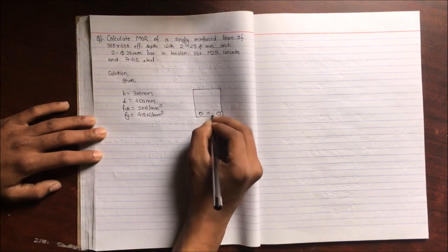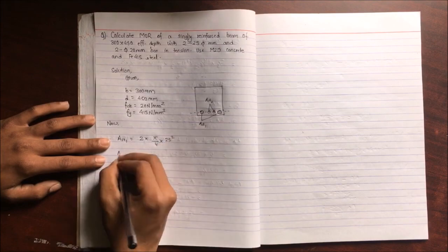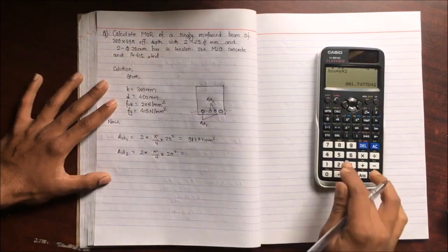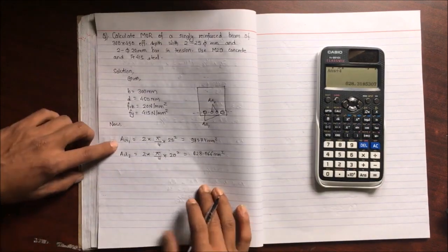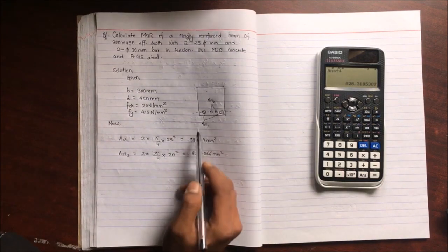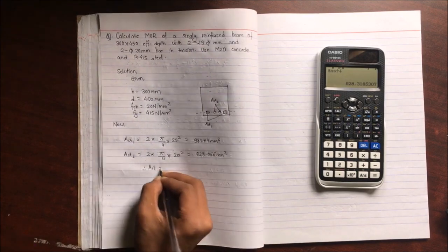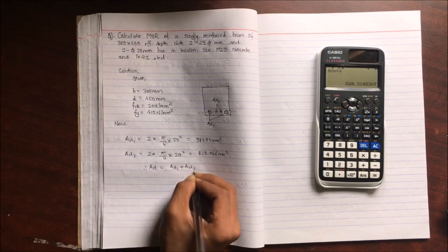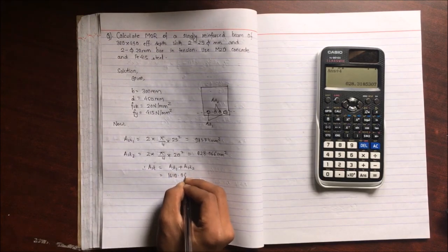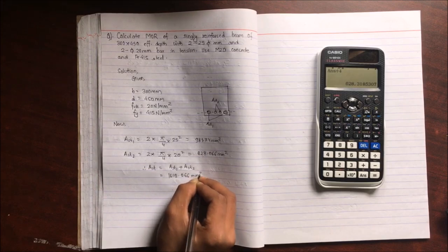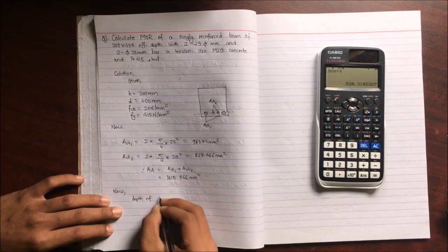Now AST1 and AST2 be the area of steel for 25 mm bar and 20 mm bar respectively. Now for calculation of AST1 and AST2, these two steels are provided in the tension zone, so AST1 and AST2 act as a combined reinforcement for the tension zone. So AST is equal to AST1 plus AST2. We get 1610.066 mm square. Also, for the depth of neutral axis,